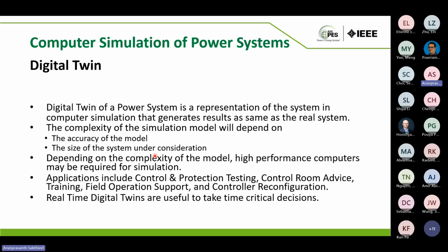The applications include control and protection testing, control room advice, training people, field operation support, controller reconfiguration, etc. Most of these applications are time critical. So having a digital twin in a real-time simulation tool would help to take those time critical decisions.